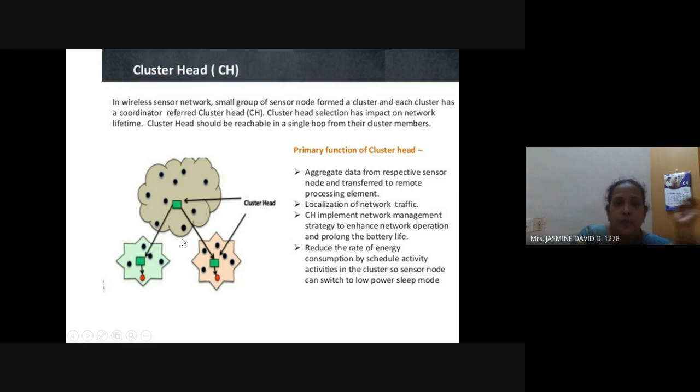Okay, so why is the energy draining? In the last class itself I told you, the cluster head is active all the time, right? So it will have some work or other to do, but the other nodes, whenever there is data to transmit, they will be transmitting. Other times they will be in the sleep condition. When the node is in the sleep mode, the energy is not drained. The energy is saved. Only when the node is in the operating condition, the energy will be reduced. Since the cluster head is in operating condition for more time, the energy may drain. So the nodes with the high energy will become a cluster head.